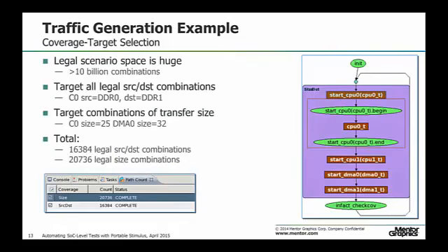Now the stimulus model that we have built is a complete and self-contained formal model of the whole stimulus space. So we can do some interesting analysis on it up front without running simulations. If we wanted to do every different size of transaction on every different data path, we would end up with more than 10 billion combinations. That's simply not feasible, at least not in simulation.